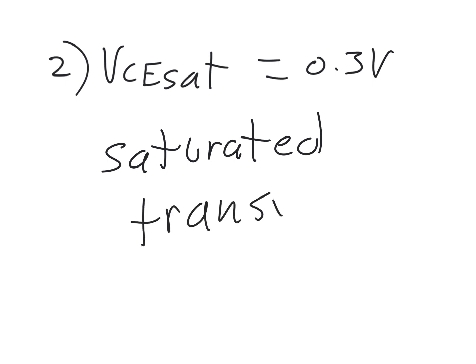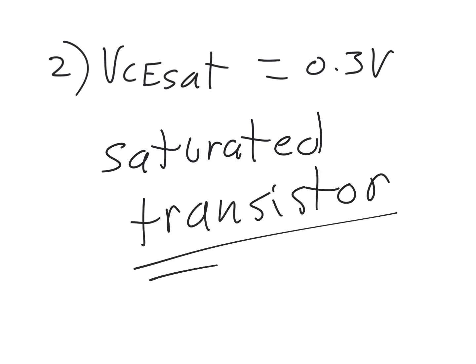So the transistor is working in the saturated region right now, and the lower that saturation voltage, the lower the gain is. So fully saturated, the gain, somewhere 10 to 30, 10 to 40, somewhere in that for the beta. Okay, so we know the beta DC is going to be low.